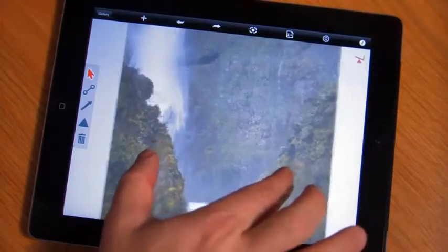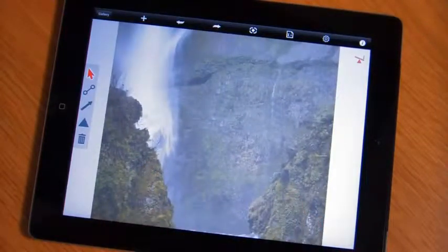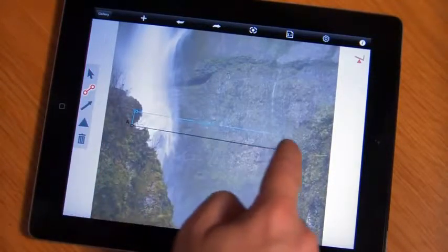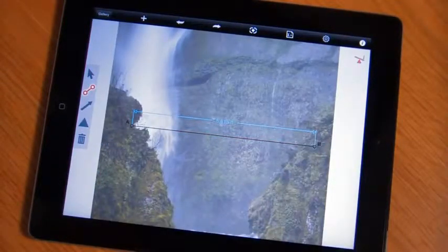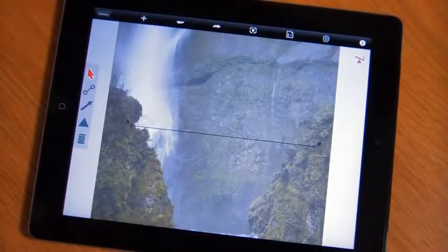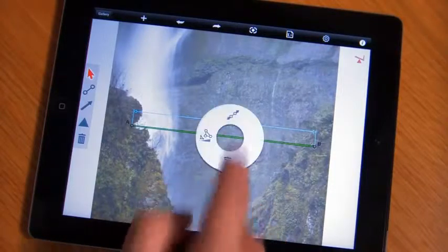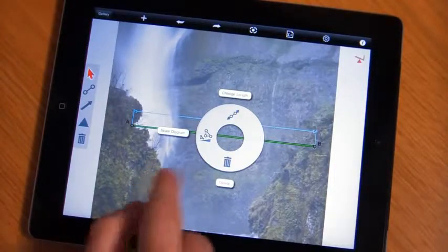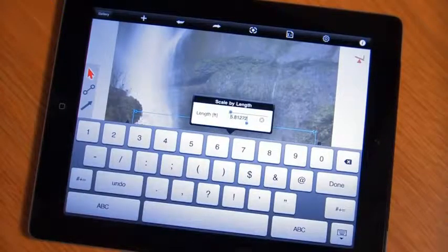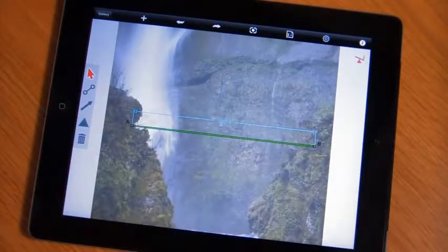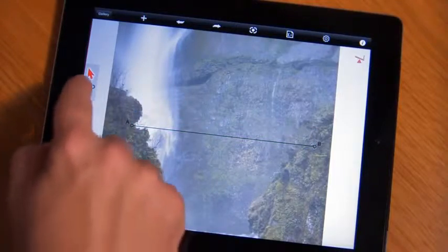Now that we have the background image, we can zoom into the area of interest. And in this case, we did take some measurements on site, and we know that the distance across the ravine is actually 900 feet. One of the powerful things we can do with Autodesk ForceEffect is scale the diagram to exactly match the scale of the photo we took, thereby getting realistic and accurate calculations. So here we hit the scale diagram command, and we say, scale the entire diagram with this line being at 900 feet. So now all the calculations will scale accordingly.